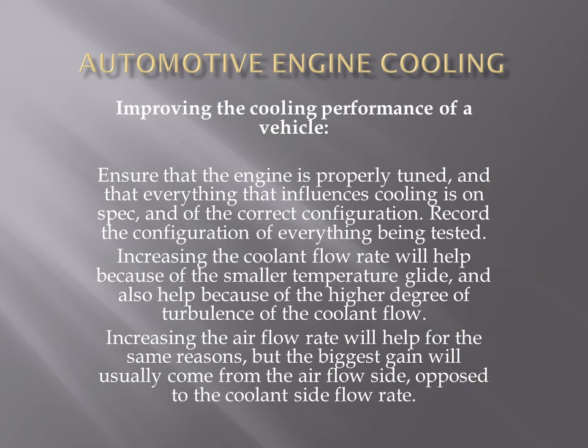Improving the cooling performance of a vehicle. Ensure that the engine is properly tuned and that everything that influences cooling is on spec and of the correct configuration. Record the configuration of everything being tested. Increasing the coolant flow rate will help because of a smaller temperature glide, and also help because of the higher degree of turbulence of the coolant flow. Increasing the airflow rate will help for the same reasons, but the biggest gain will usually come from airflow side as opposed to the coolant side flow rate.